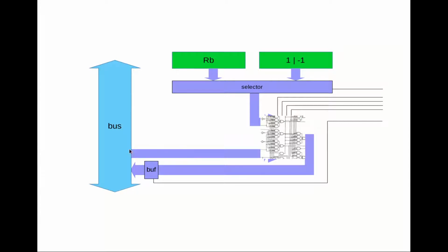And so if we disable the A register's output onto the bus, then those input wires won't contain any sort of valid state anymore, and therefore nor will the output wires. And so even if we enable the bus at that point, we'll be outputting total nonsense onto the bus. We won't have remembered what that was. This component doesn't remember, it doesn't have any sort of memory. It's purely combinational logic.